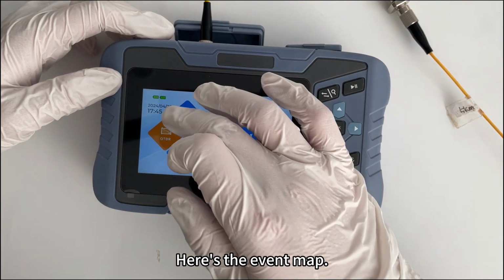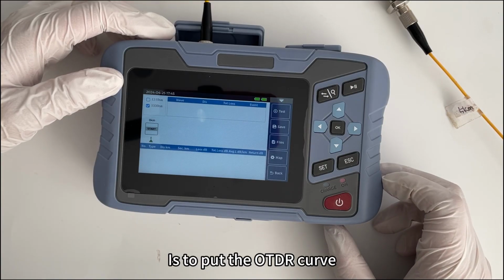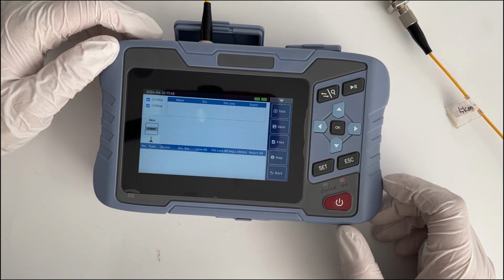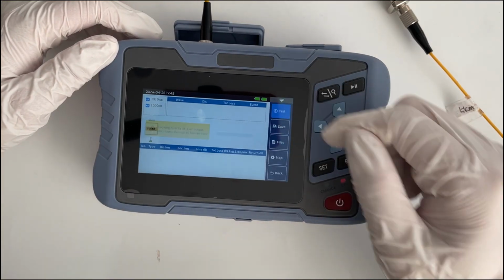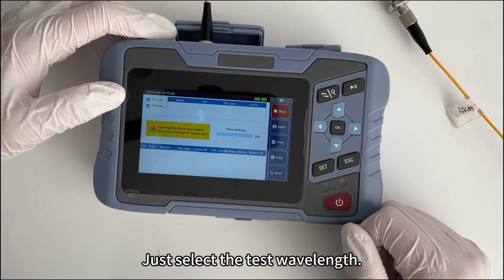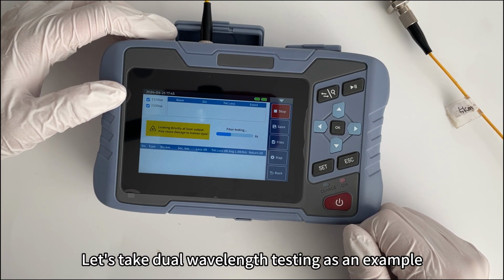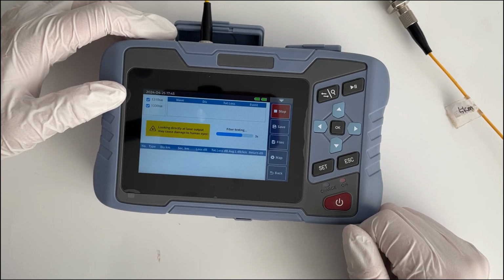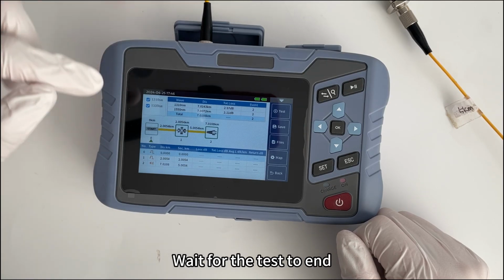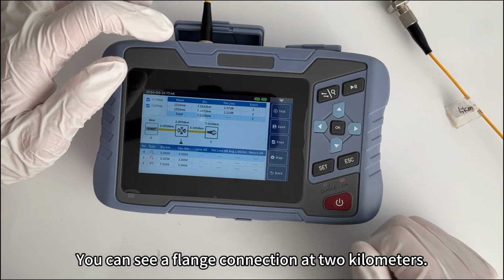Here's the event map. The event map puts the OTDR curve on display graphically. For the event map test, just select the test wavelength. Let's take dual wavelength testing as an example. Waiting for the test to end. You can see a flange connection at 2 kilometers.